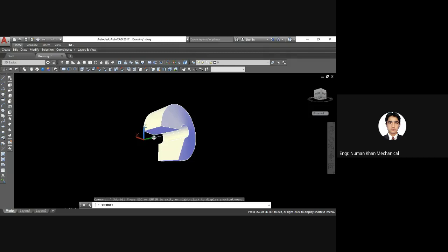So it is just like an extrusion, but we are extruding it along an angular, circular path. All circular, axially symmetric objects can be made using the revolve command, in which the cross section is uniform and you just need to revolve it around a particular axis.